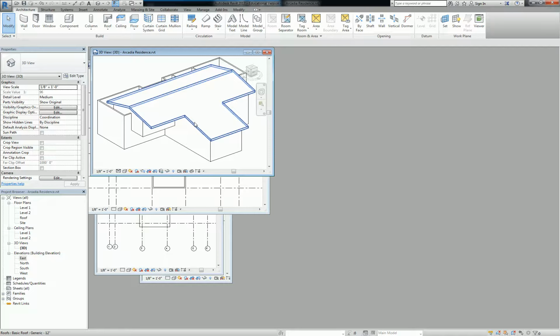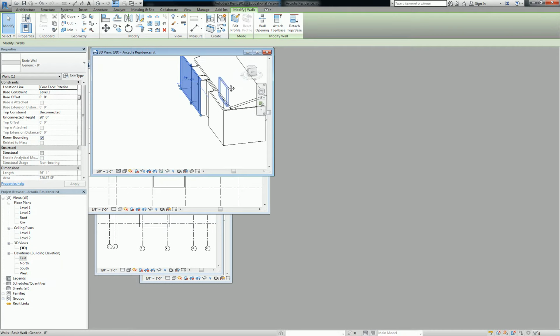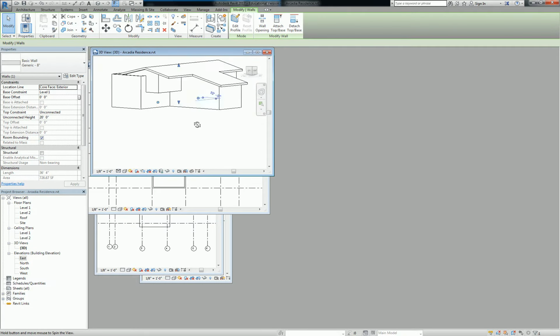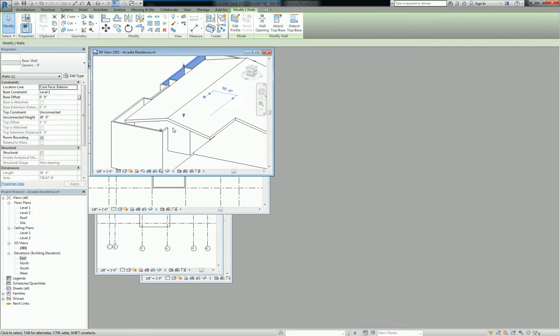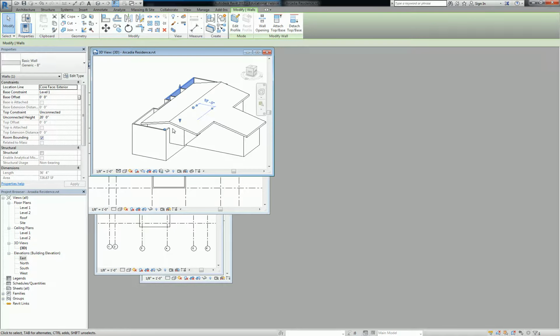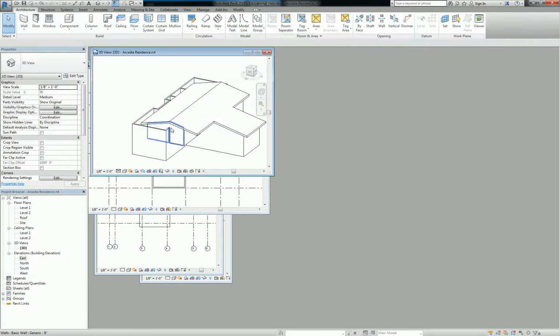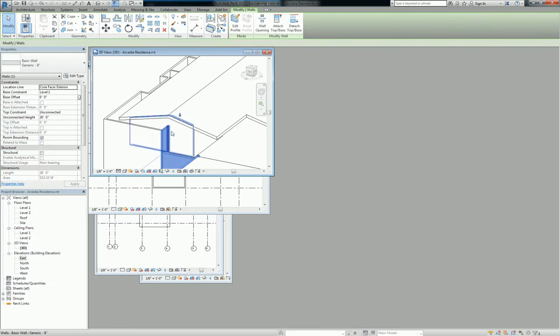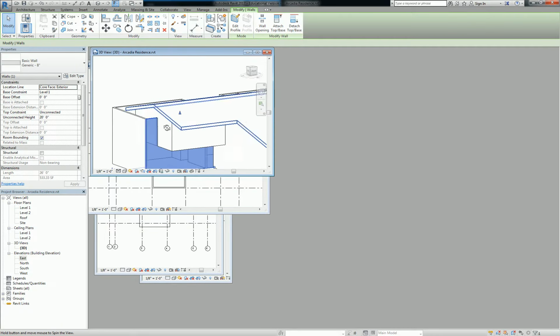But you guys have a back wall here on the building that's really not at all masked out the way the building should look. So what I want to do is show you that those walls are currently not associated at all with any top constraint, and they default to 20 feet, which is much too high. So we're going to set all of the exterior walls along the back of the building to have a top constraint of the second floor. And then we're going to add an overshoot of like 3 feet to start with. Okay, so that looks like this. I'm going to select, well, this wall actually needs to be broken.